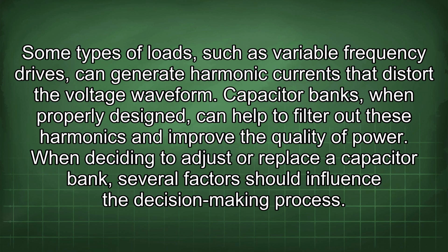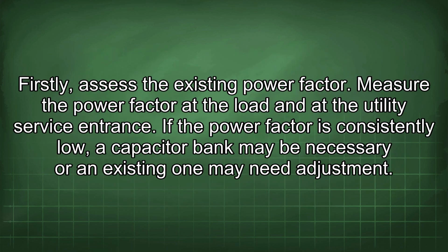When deciding to adjust or replace a capacitor bank, several factors should influence the decision-making process. Firstly, assess the existing power factor. Measure the power factor at the load and at the utility service entrance. If the power factor is consistently low, a capacitor bank may be necessary or an existing one may need adjustment.